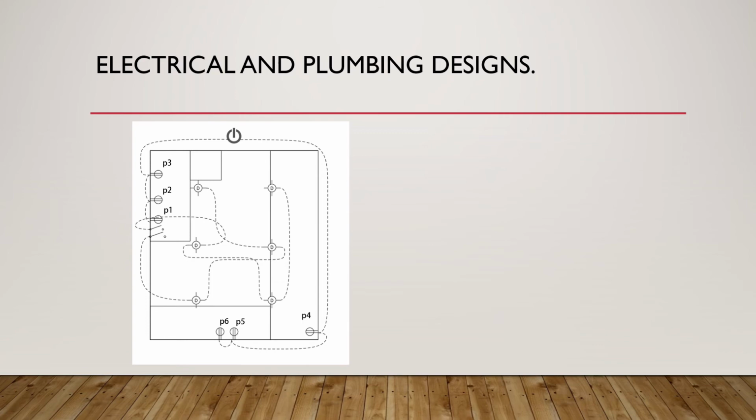Outlets 1 to 3 are placed there for the use of small appliances since this is the working area. Outlet 2 is to be placed in the shelf below so that appliances can be used in the shelves and not only in the countertop. Outlet 4 can be used to give power to electronic devices such as cash registers and monitors. Outlet 5 is to be placed on the floor of the cart to provide power to 2 refrigerators. Outlet 6 is placed on the counter and can be used as the operator sees fit. The generator was sized and found that it requires a generator with a minimum 6.5 kVA.